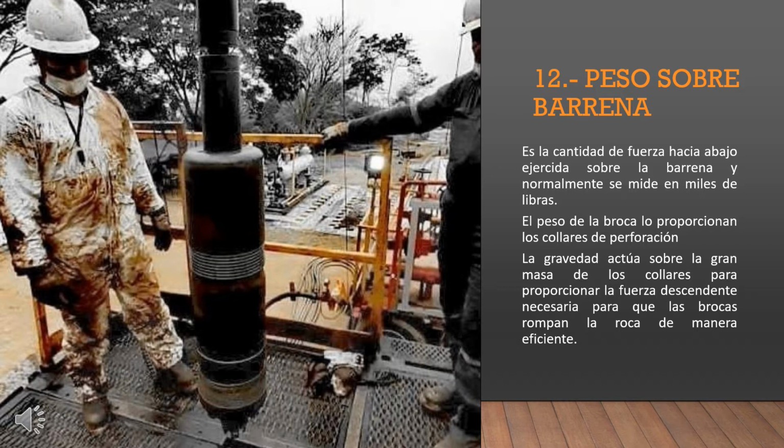The weight on bit is the amount of downward force exerted on the drilling bit and is normally measured in thousands of pounds. Weight on bit is provided by drill collars, which are thick-walled tubular pieces machined from solid bars of steel.